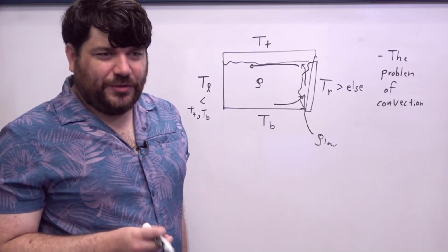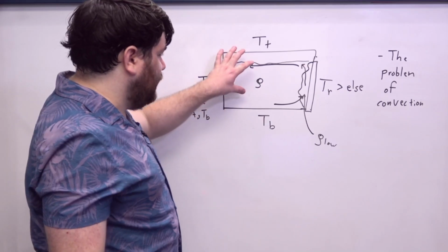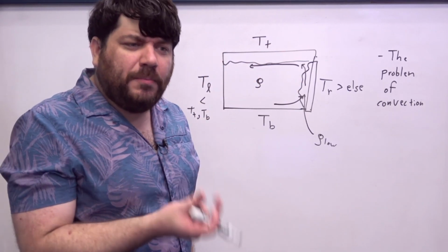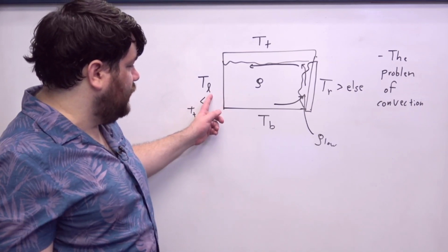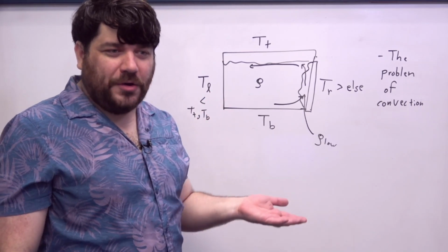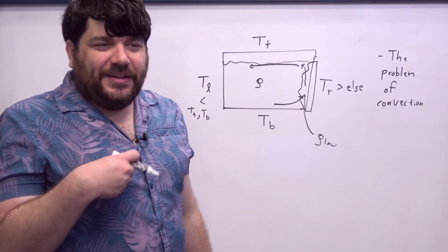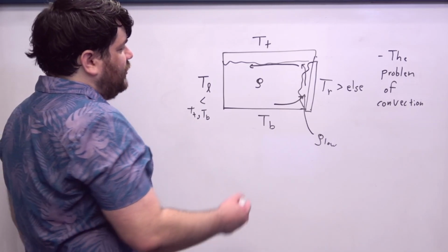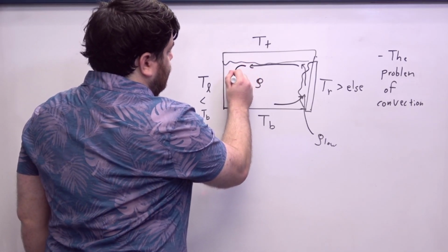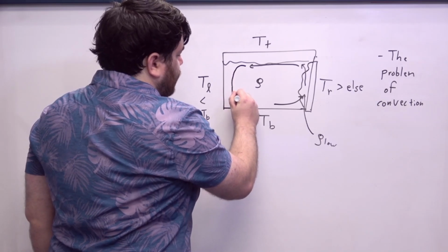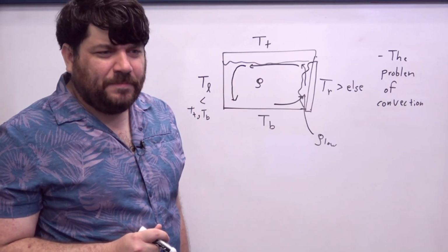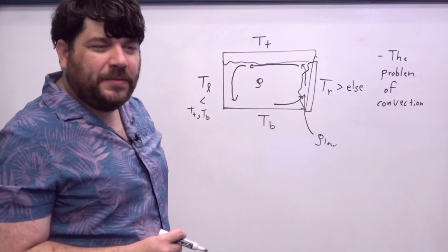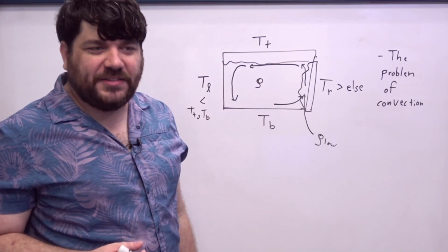And as that temperature starts to settle down, right, as the temperature of the chunk of fluid that's been flowing around the system starts to go back down to a background temperature, or if you assume that this temperature TL is lower than the background, then it starts to become lower. Eventually what happens is that the buoyancy effect starts to go away, right? And so the liquid starts to settle down and will, in general, start to flow downwards, okay? If this temperature is the same as the background temperature, then it'll kind of spread out, but the general trend is more or less the same.